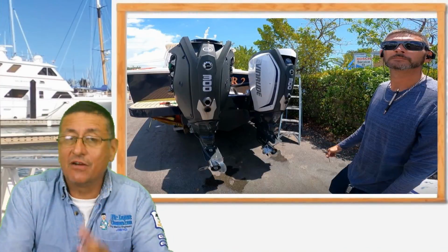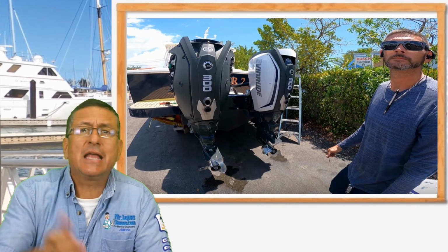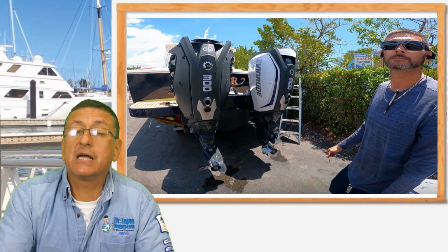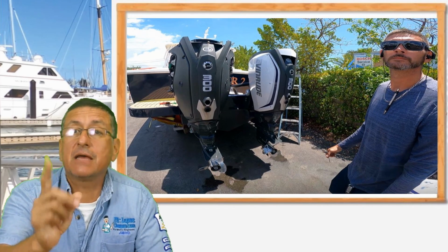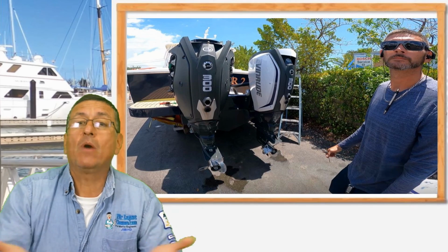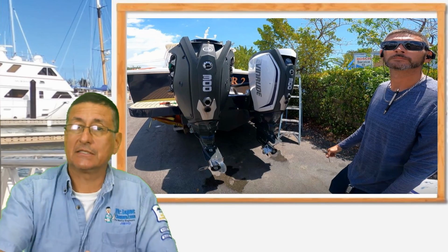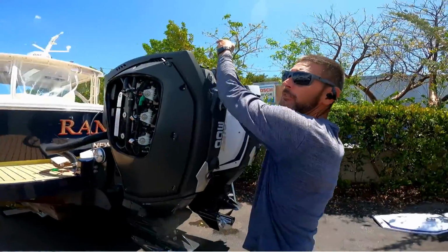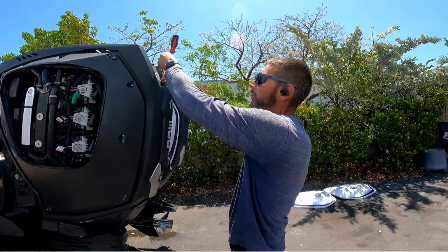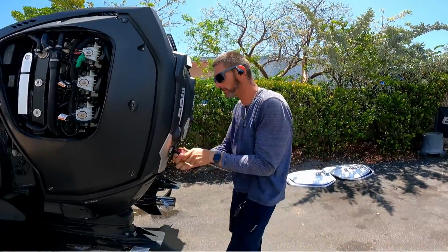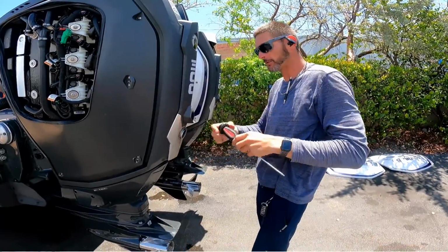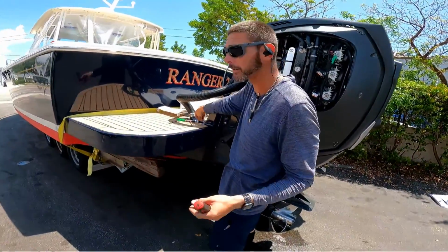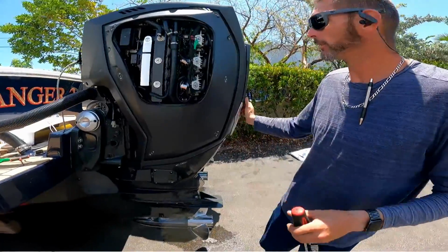Okay, this is the complaint of the customer. After that, Danny disassembled the engine and removed all the plastic in order to start checking. The first step is to check the quality, the integrity of the harness. What is the first step? First step, we're going to go through and just check to make sure that there are no chafed harnesses anywhere, because we can go through and dry test everything with the laptop and it's all functional. Okay. So we're going to go through and see, maybe with it running, if there's a vibration and a wire that started to chafe on the block, short. We're going to go that route first and see what's going on.